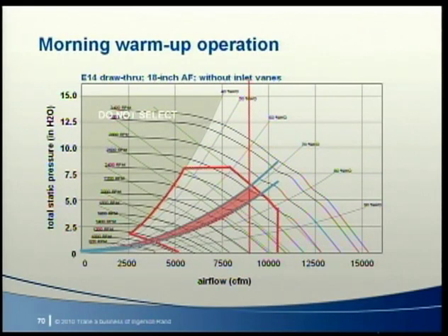One common control approach forces all VAV boxes wide open. This causes the system curve to drop, as shown, for example. With duct pressure control disabled, the fan operates at its maximum speed. If maximum speed equals design speed, the fan tries to deliver almost 11,000 CFM at 2,600 RPM. This exceeds the airflow limit. Either a larger fan or, more likely, a larger air handler would be needed for this much airflow. So if you set a max speed, be sure it's not set too high.